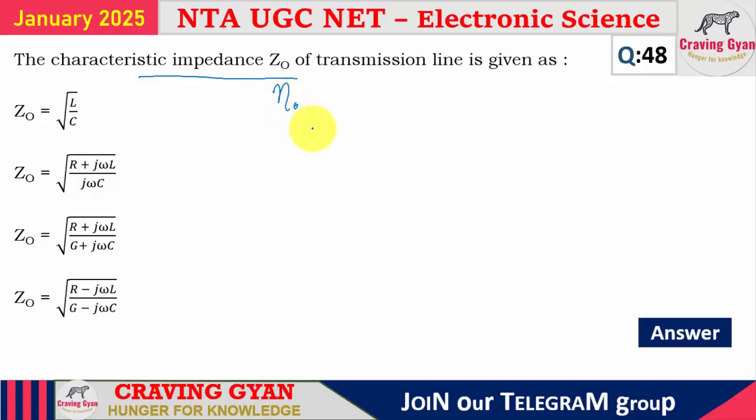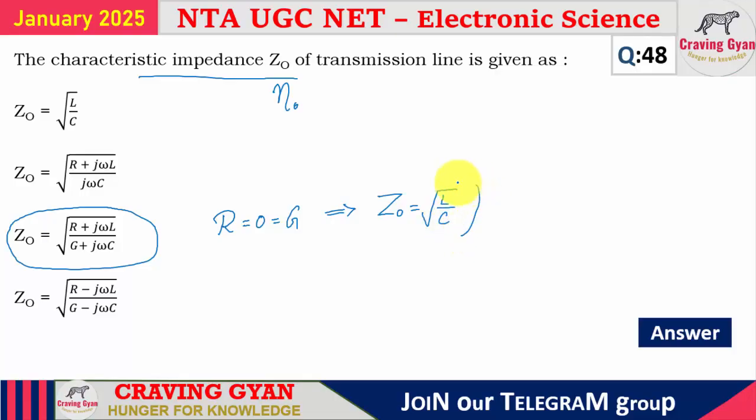Nothing else. So this Z0 is given by square root of (R plus j omega L) all divided by (G plus j omega C). But under the ideal scenario, R equals 0, which equals G. So what you're going to get is Z0 equals square root of L by C. This is not valid in all the cases, but under the ideal scenario, this Z0 is expressed as square root of L by C. In order to confuse you, the first option they have given is square root of L by C. The moment you try to opt for square root of L by C, your marks will be deducted.